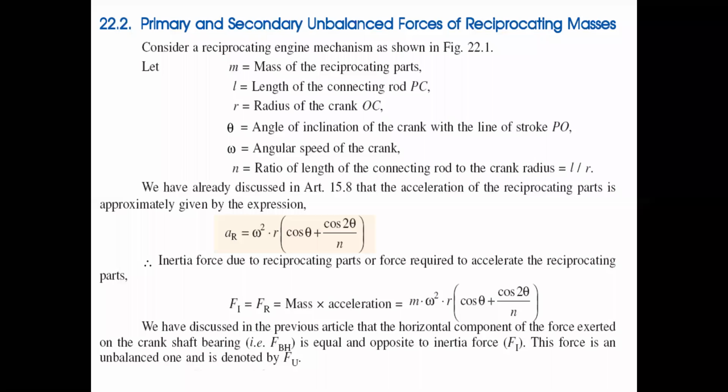What is its value? This was already covered in our earlier subject, COM. The reciprocating acceleration of the piston, a suffix r, equals omega square r into cos theta plus cos 2 theta by n.